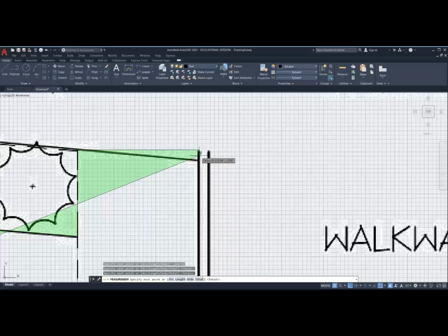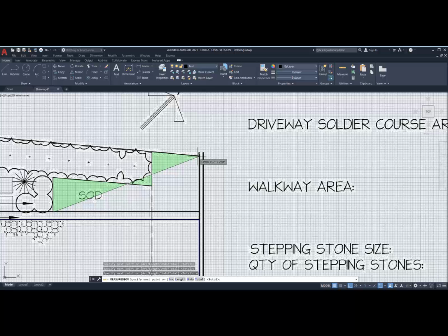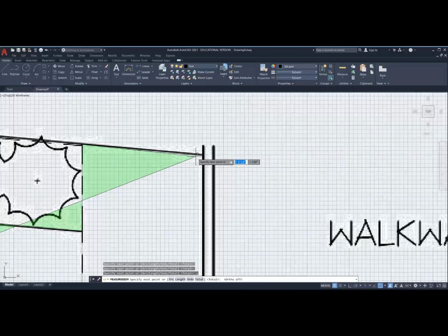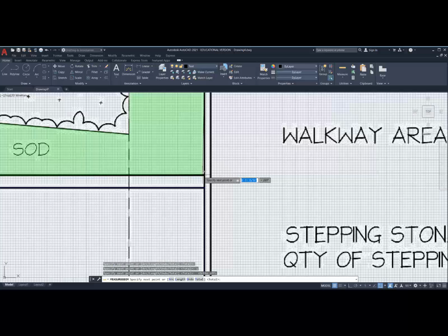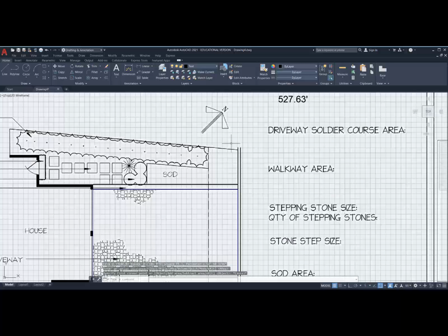So I will undo that and take off my F8. And now I can go into any direction. So we could use this technique. I'll press enter, and it's pretty accurate. There's my area, 91.9791 square feet, or about 92 square feet. The problem with that is after I finish that, I can't go back to it. There's nothing that remains there.